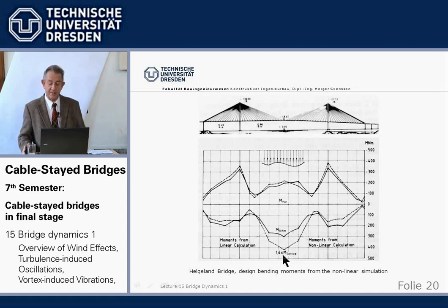It can come up that, due to the cracking and reducing of restraint moments, the nonlinear or second order moments are smaller than those linear with uncracked sections. So this is an excellent result, which enables us to check that the wind stresses are not bigger than those from live load and are within the permissible range.